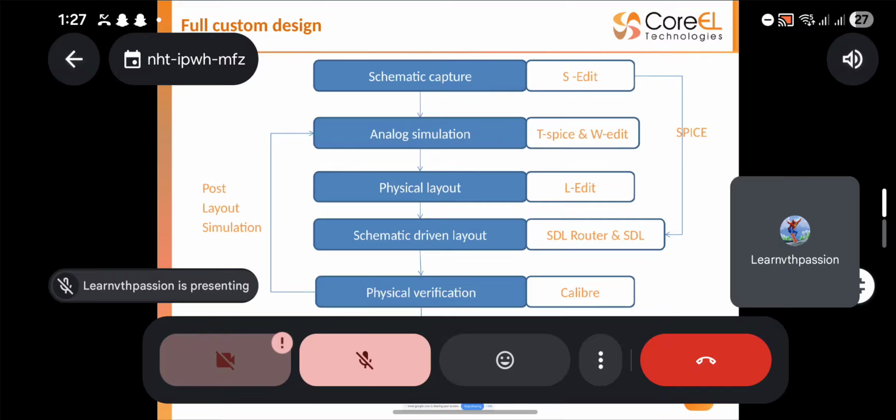Whatever connection I'm telling you, you have to make the internal input connection, output connection, VDD connection, and ground connection. There is the option called route all. Even this was present in the Tanner previously, 5 years back. Now they are giving that option only for the industries. For the academic, they have removed it. If you had that route all option, even that connection is not necessary. Once you load the HDL navigator, it will give you a ready layout. You just want to go to the verification. No connection, nothing. Any errors if it is showing, then that might be the errors in the netlist formation.